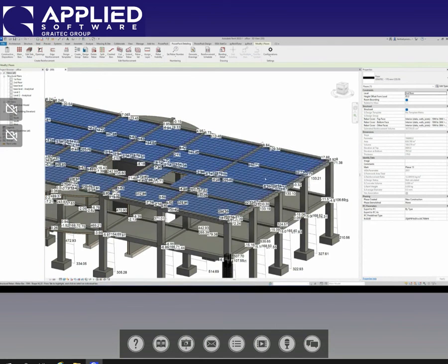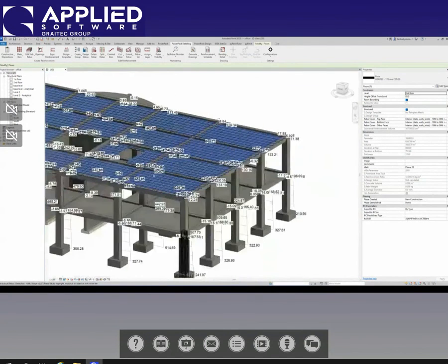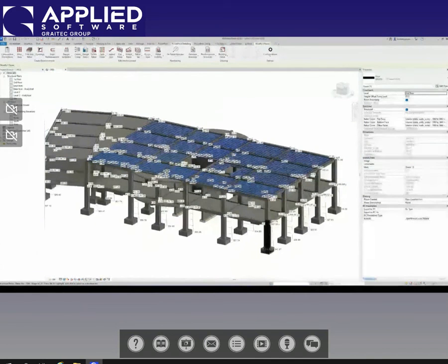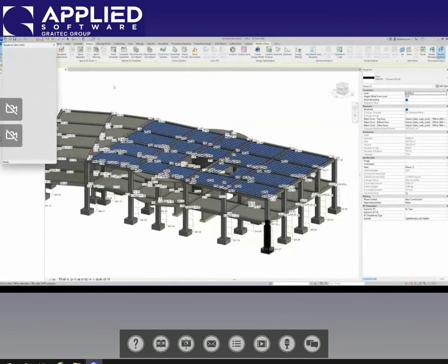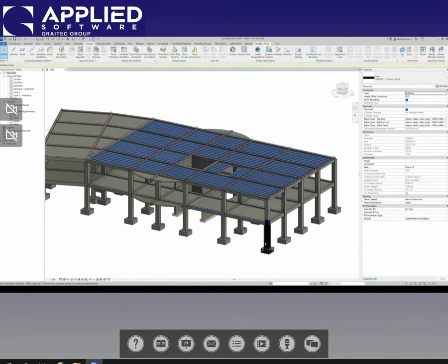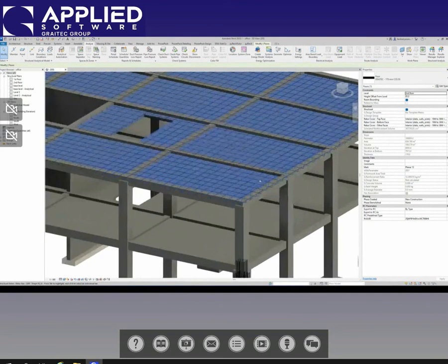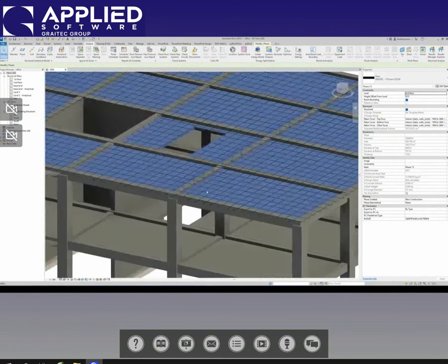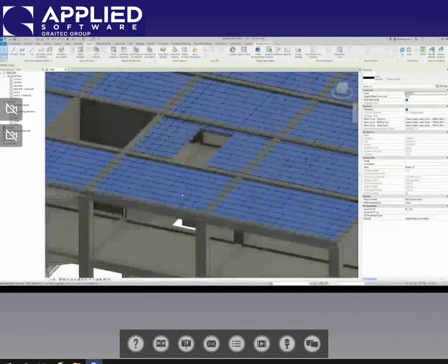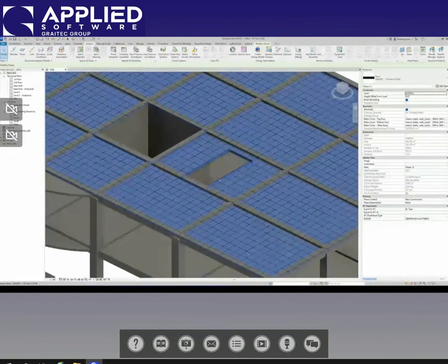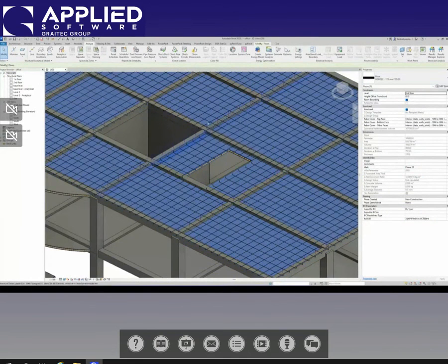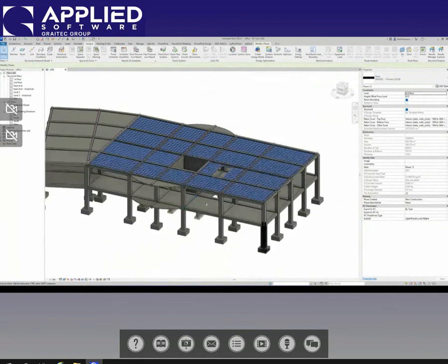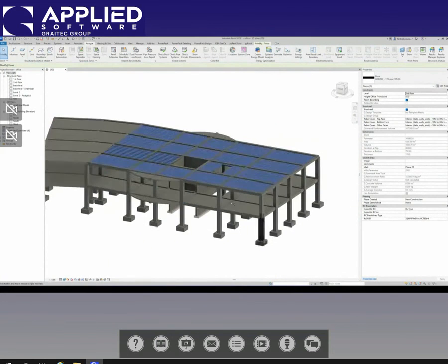So we can actually perform the same scenario. So just here, I will hide my diagrams. So it's going to be more clear, as you see here, the rebars. And the good thing is, our tool here, the Power Pack, will automatically detect all of the openings that you have here. So you can actually perform the same scenario for the top rebar.